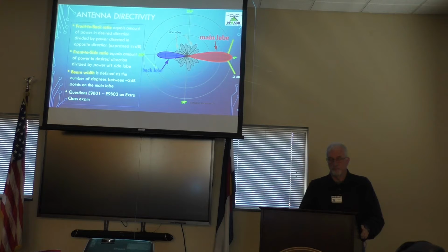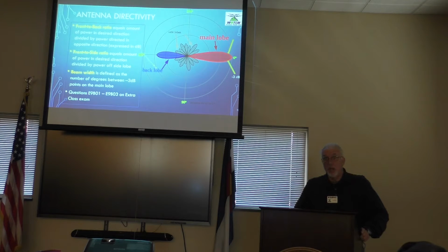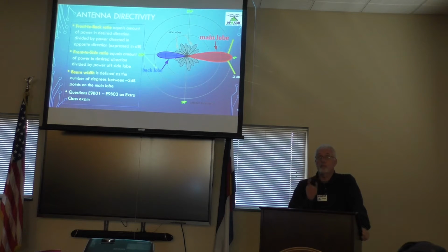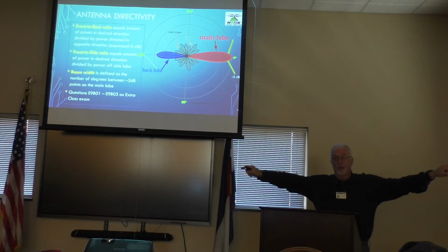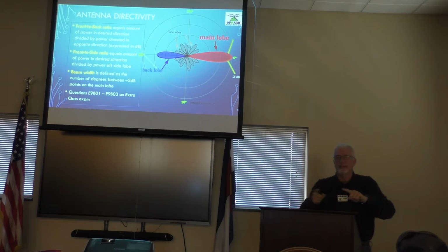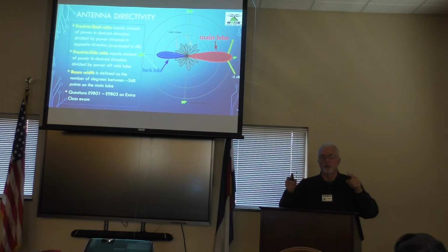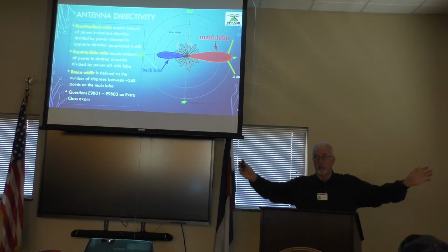And a follow-up on that one, is a quad construction more effective than a Yagi? I'm going to say that is a gigantic, it depends. Because in principle, they're doing the same thing. Instead of a long horizontal, you put those wires in a square, it doesn't have to be a perfect square, but the answer is that it will provide directivity, it will provide gain in a particular direction, it will reduce reception or transmission off the side or to the rear.